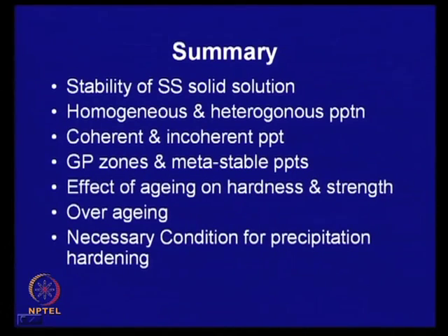We have seen that if we can promote homogeneous precipitation, then the precipitate distribution is more uniform and they are likely to give a better precipitation hardening. We looked at heterogeneous precipitation and at the potential sites of heterogeneous precipitation. Then we have seen there are gradations.